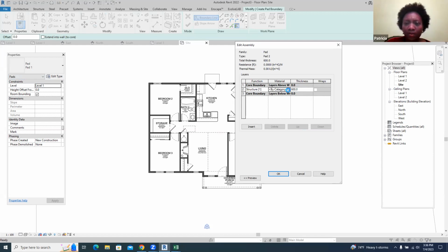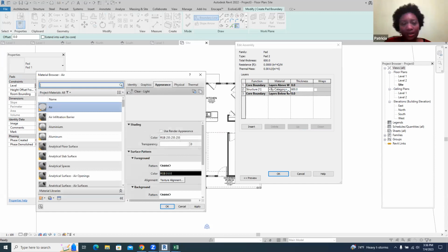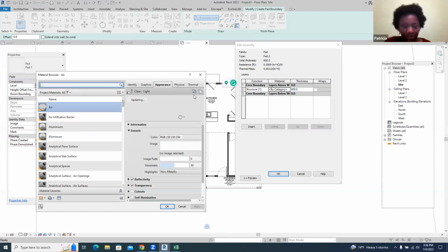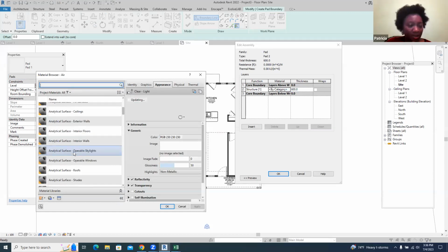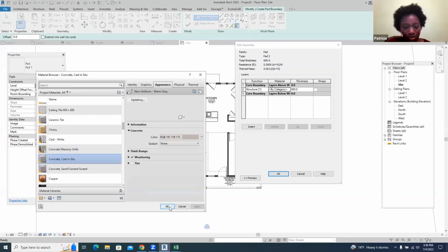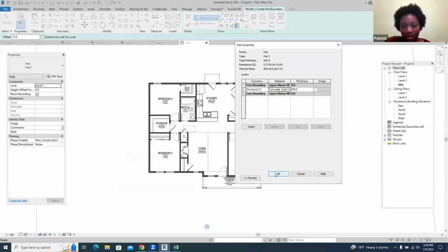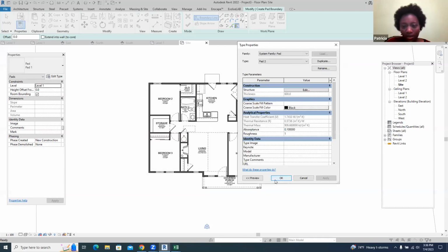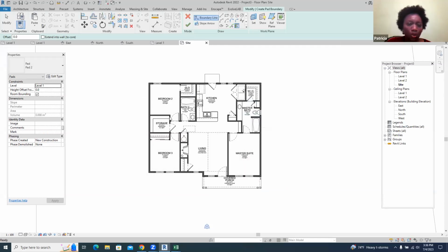So for material, you click on the space beside category. It will not just appear. You have to click on that space and then it will come up. And then we said we want to do concrete cast in situ. Okay. And then a third time here. So when I go along this line now, I'll get it. I have to pick what I'm going to draw it with. Do I want to use box, all that, or the line?